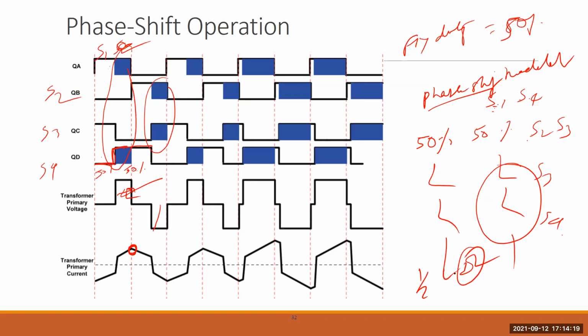The average value of this I will go down a bit, but you can see the peak value where the change is happening, the switching turn on and turn off, you can still maintain that high. So this half L i square is still higher than C V square, and this will offer you a higher soft switching range, because you are maintaining the peak current where the switching is happening.